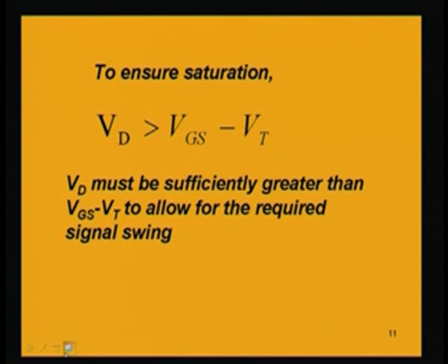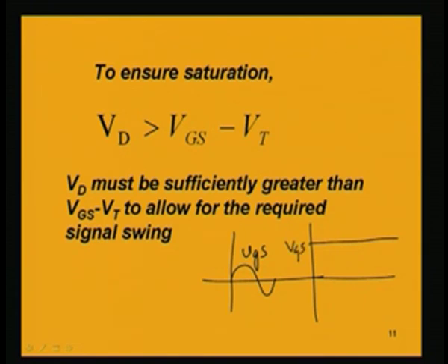That is because we have a signal swing, because of the swing in the input AC voltage. If we have a DC VGS here, because of the signal we will have the drain current small i d superimposed on the capital I D, which is due to VGS only. So, for application of only the DC VGS, suppose we have VDS as this one, capital V DS means the DC voltage due to this VGS only.